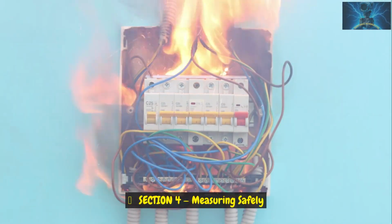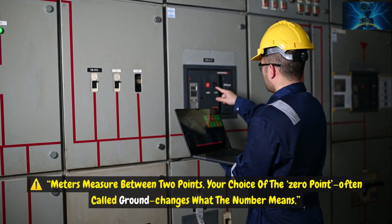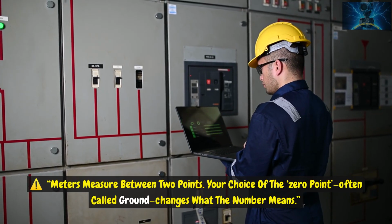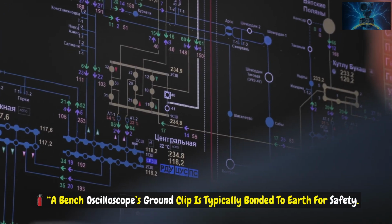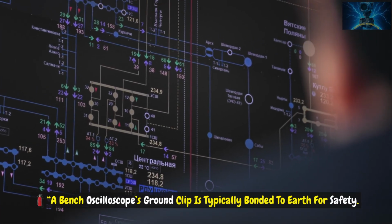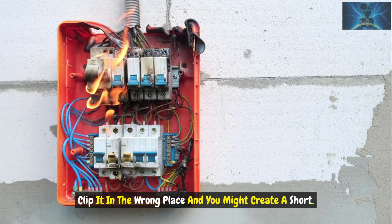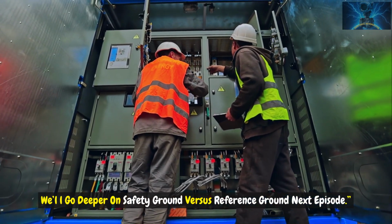Section 4. Measuring safely. Meters measure between 2 points. Your choice of the 0 point, often called ground, changes what the number means. A bench oscilloscope's ground clip is typically bonded to earth for safety. Clip it in the wrong place and you might create a short. We'll go deeper on safety ground versus reference ground next episode.